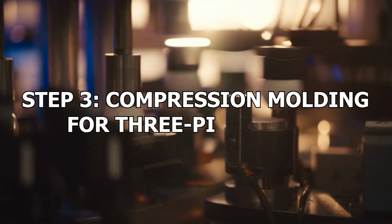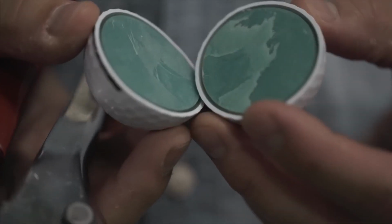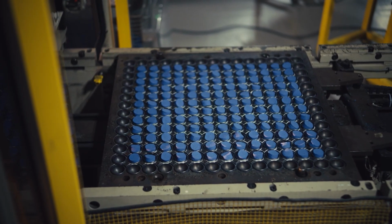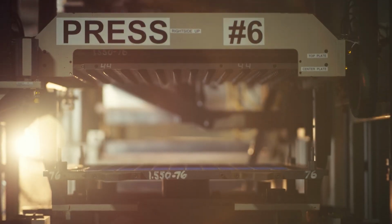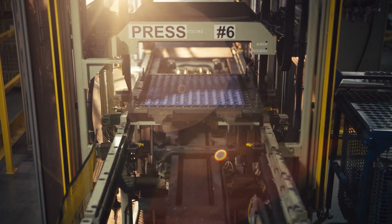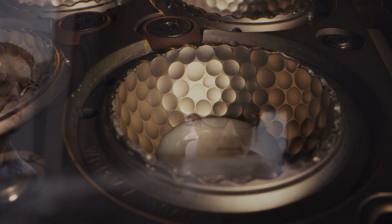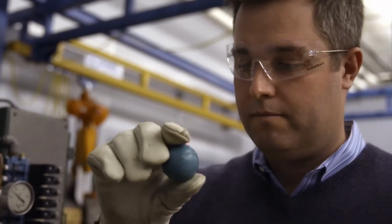Step 3. Compression molding for three-piece balls. Three-piece balls, due to their more complex structure, undergo compression molding. Initially, the cover material is injection molded into two hollow hemispheres. These hemispheres are then positioned around the core and heated. A mold then presses them together, fusing the cover to the core and forming the dimples. This method prevents distortion and breakage of the rubber threads within the ball.